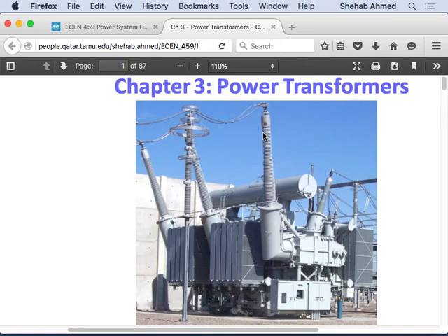So you need a higher voltage. Basically, you have a live conductor coming in, a live conductor with voltage on it, and the chassis of the transformer, the metal itself, is grounded. We will talk about why it's grounded when we talk more about protection, okay? But typically the body itself is connected to ground, mainly because, let's say a human passes by and touches the body, and it's not grounded, and let's say a wire inside broke its insulation and is touching the chassis.